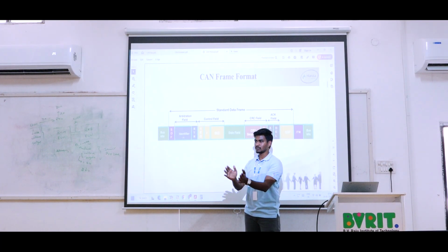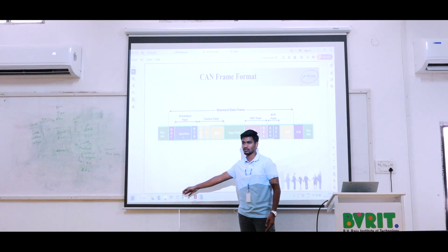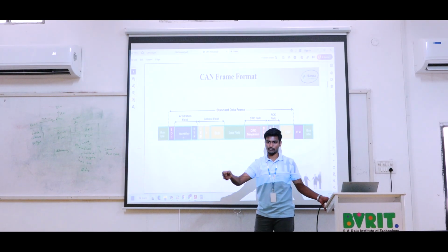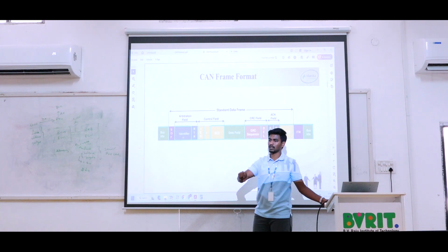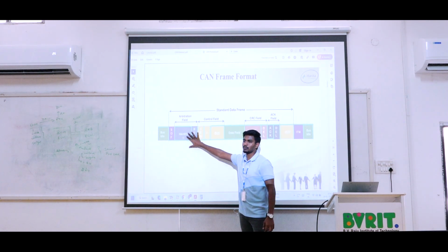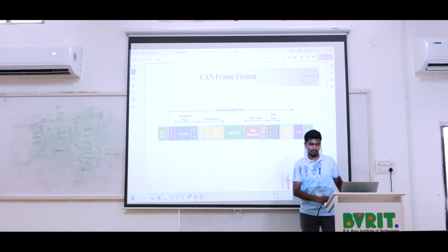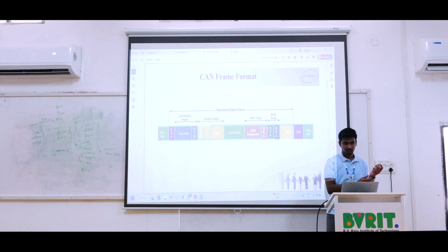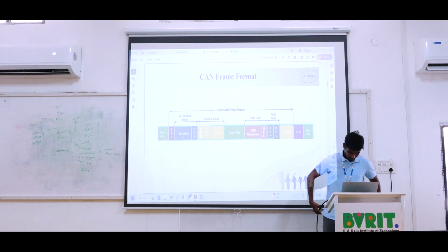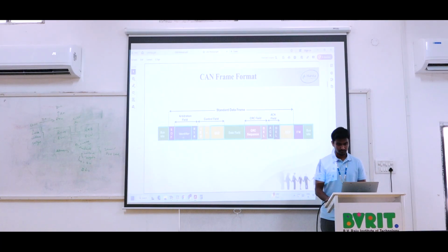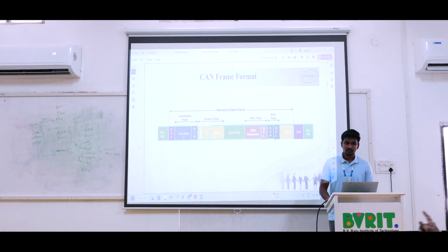After creation we are going to upload the same to our test tool, the CANoe tool. At that time we will get the transmission. If we need to transmit ID 500 and ID 400, who will get the arbitration? That is the point. For example, you have airbags, a tire puncture signal and an AC signal. Out of the three, which has the most priority for safety? Airbags. So for the airbags we give the least ID. That least ID is sent first, so it is executed and the airbags are activated. Later the next ID is activated, and then the next ID.